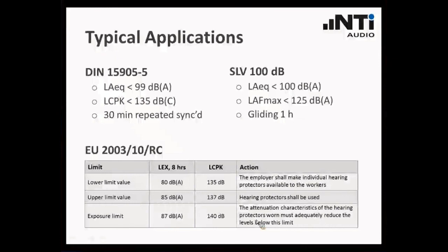Maybe you have asked yourself, what is LEX standing for? In this case, if you read the standard, you will see that this is the same as the LAeq for 8 hours. So this is another example how you can familiarize yourself with the corresponding requirement by reading the standard and understanding the corresponding parameters.